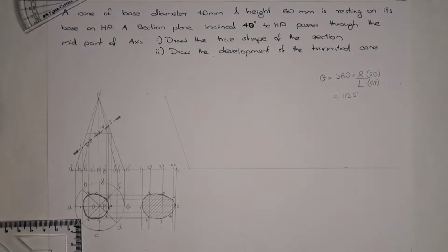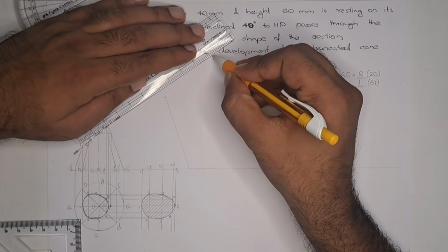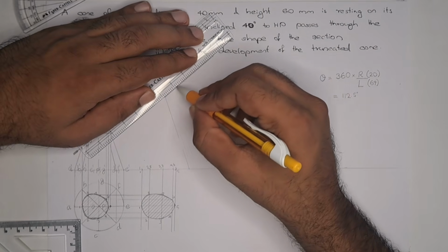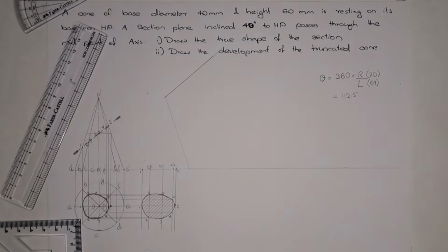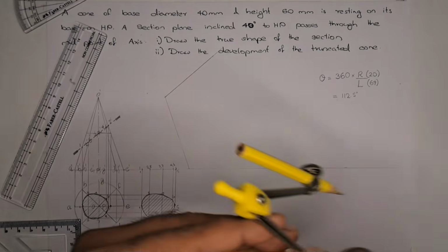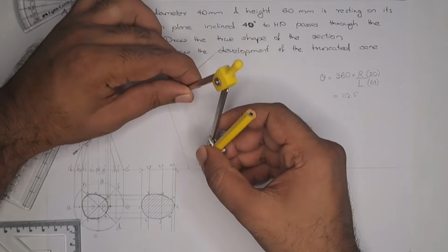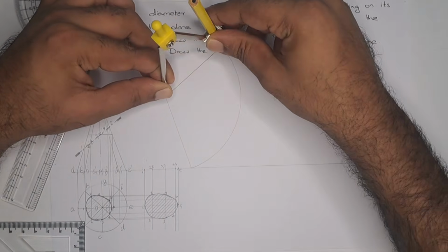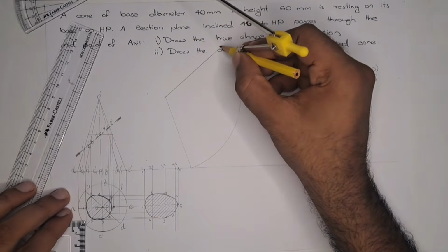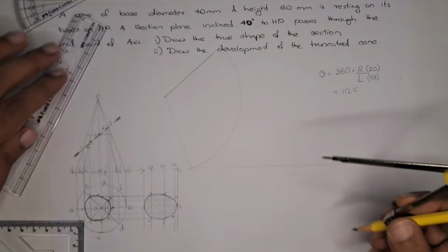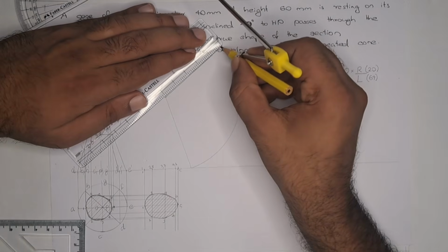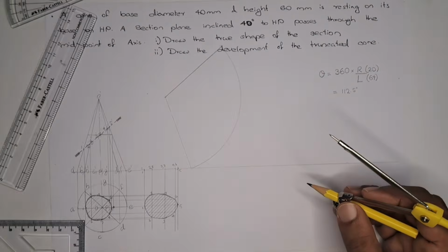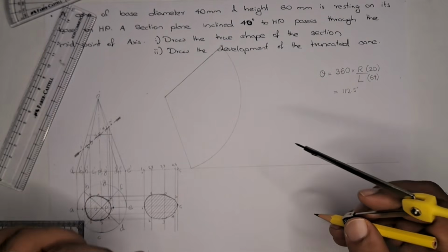Need to draw the line over here, and we can even mark the distance and close the circle arc. The next thing we need to do is to divide this arc into 8 equal parts. For that we are using the angle bisector.